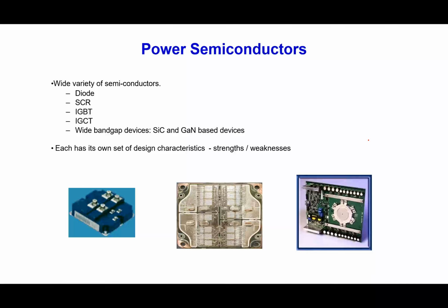Yeah, several megahertz. Silicon carbide devices can also be switched at high frequencies in the order of several hundreds of kilohertz. Okay. But silicon carbide devices are available at higher voltages. Gallium nitride devices are not; the maximum available is 600 volts. So if you want to operate at high frequencies of the order of, say, 500 kilohertz to 1 megahertz, then gallium nitride is the best. Okay.